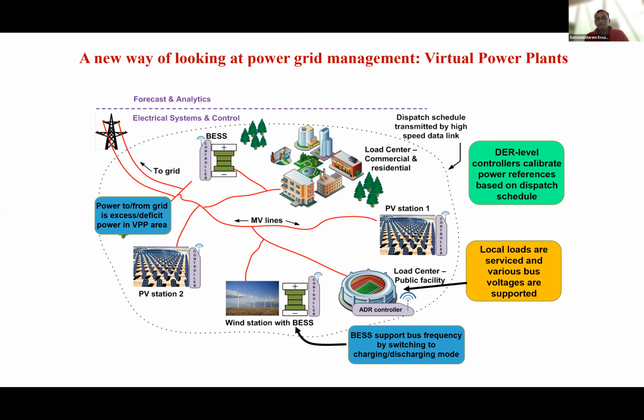Because you can reduce the power consumption, or turn it off for 10 minutes, 15 minutes. It's a thermal system, so it's not going to fluctuate very quickly, right? So such dynamic increases in demand can be met by using automated demand response systems, right? So you're responding to the increase in demand, and that is the so-called DR, demand response, right?